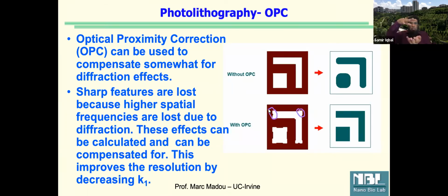So when the light is projected, it gives us very sharp features like the one shown here, instead of rounding off. This is an issue when we are going down, reaching the diffraction limit, right? Waves construct and interfere with each other. So these are physical ways where we have been calculating what compensation we need to add into the feature, and hence, after all the interactions of light, we end up having good feature translation.